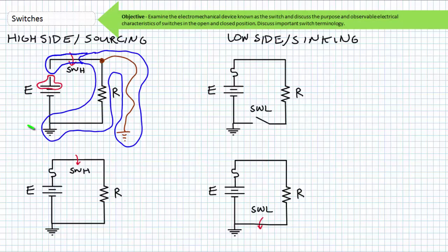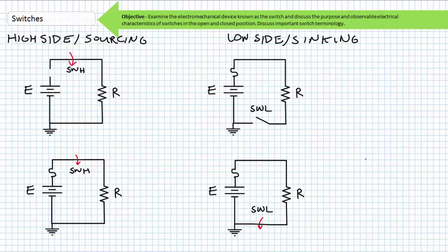The presence of an intentionally grounded source and a fuse in series with the load allowed for the detection and resolution of the short in a high side switching arrangement. At no time did the electrical load unexpectedly energize. Now consider the exact same scenario for a low side switching arrangement. Consider what would happen if an errant piece of conductive wire accidentally bridged the electrical load and something connected to ground at this bottom terminal.